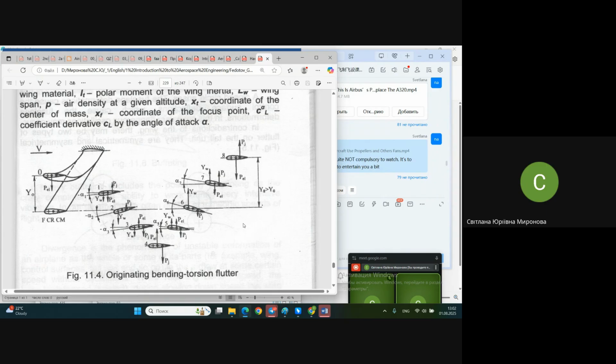And due to occasional factors like additional energy of wind, for instance, or additional energy of relative wind because someone increases the thrust. They happen at some speed, but it's not a fixed value of speed for all aircraft at all. This critical value of flutter depends on the different structures of airplanes. It depends on the airplane's general structure, and it depends on aircraft stiffness.